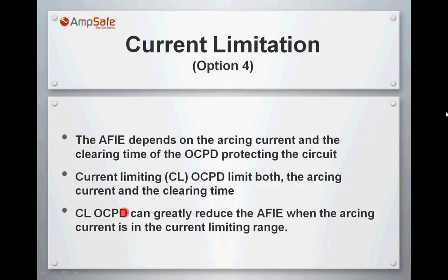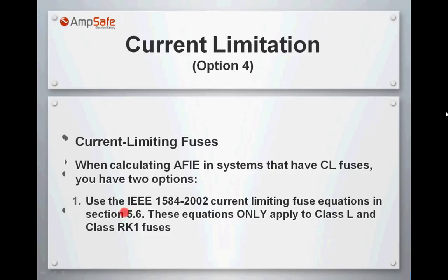How can we consider the current limiting effect of, let's say first, fuses? And remember, not all fuses are current limiting. I still see some old designed fuses, like one-time fuses, okay? And even renewable fuses I still see sometimes, which are very old design fuses, 50 years ago or so, and they are not current limiting.